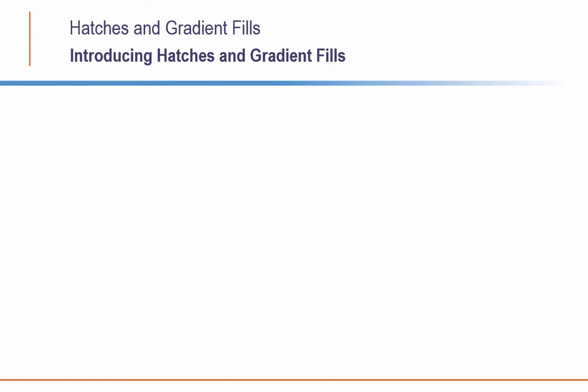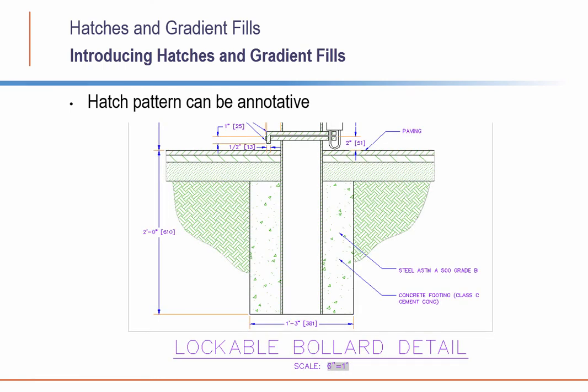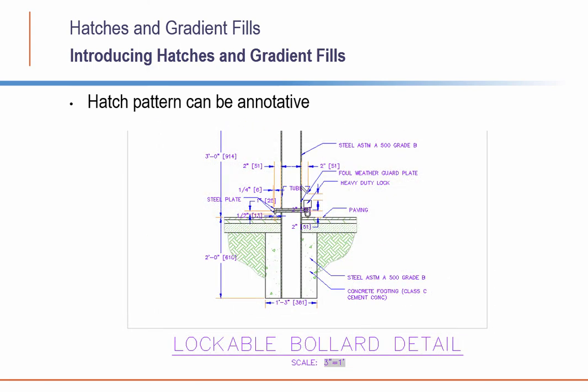Hatch patterns can also be annotative. That means the hatch pattern rescales automatically if the scale of the drawing changes, so that the hatch pattern always displays and prints at the size you specify, regardless of changes to the scale of the drawing.